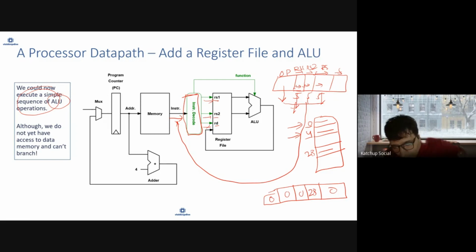Now, outside of memory, your instruction will look like this. Now this instruction has to be broken down. So you have to tell the register file which address has to be read: 0 for the first operand, 4 for the second operand, and 28 for the result. So this full 32-bit instruction is broken down into these parts, and this is known as decoding in a simplistic case. In a complex processor, the decoding may involve multiple more elements. So this then goes into the register file.